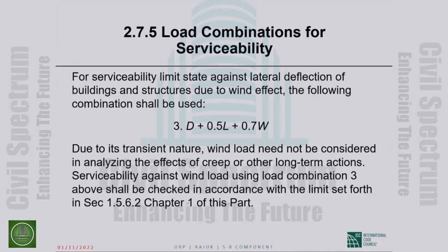For serviceability limit state against lateral deflection due to wind effect, the following combination shall be used: dead plus 0.5 live plus 0.7 wind. This 0.7 wind is interesting, and at the same time it needs to be explained, and I will try to.